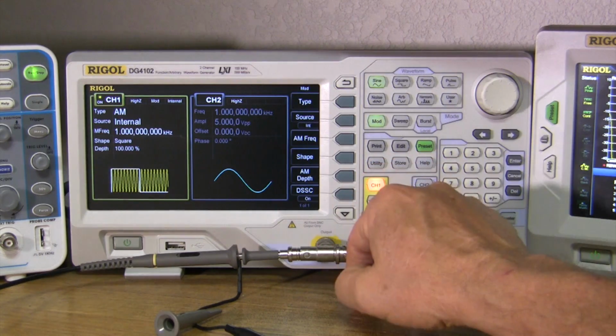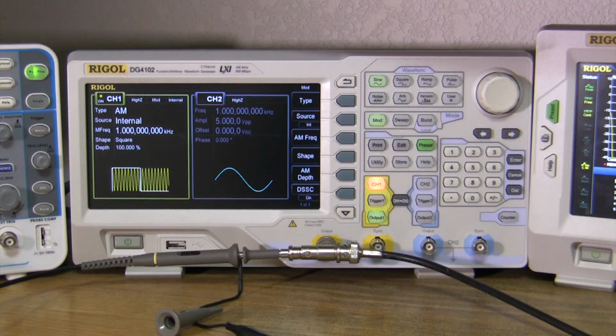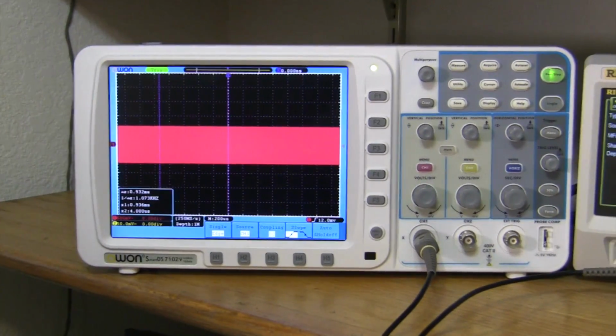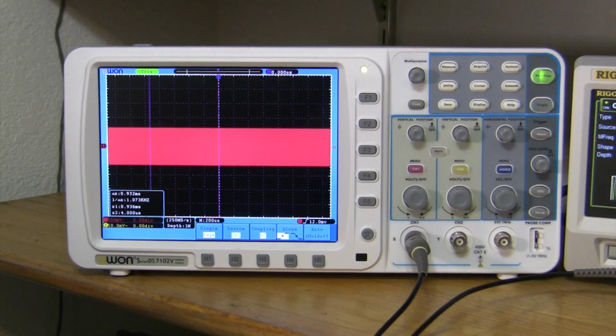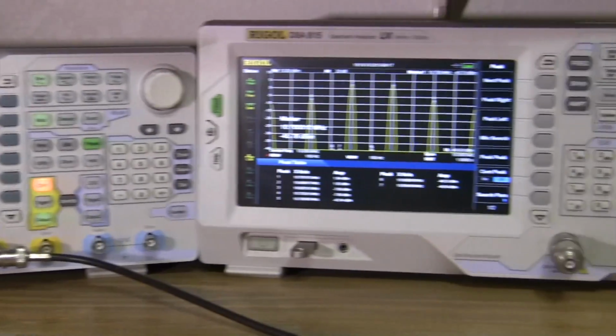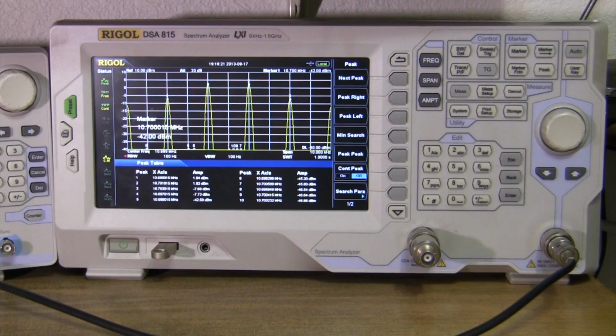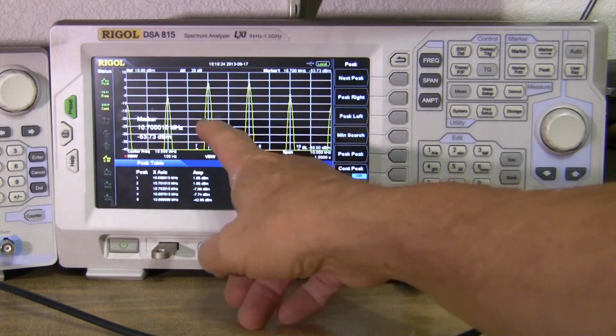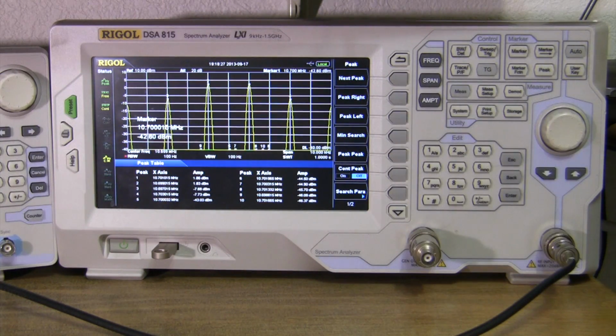And the square wave with double sideband is going to show the harmonics of each of these tones, because it is a square wave after all. And of course, because it's double sideband, it's going to have sidebands out of phase, so it pretty much looks like a solid line. And here's the harmonics. The harmonics of this one are going up, and the harmonics of that one are going down, or subharmonics, whatever you want to call it. And that's because of the square wave nature of what we're putting into this thing.